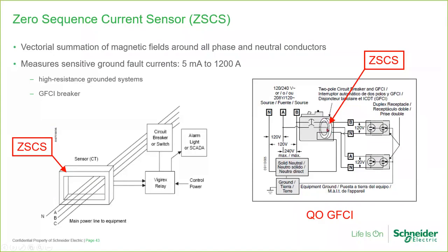That's why these breakers have pigtails, because unlike a normal breaker where you can just bring the load neutral to the solid neutral bus bar, we have to bring the load neutral to the breaker so that it's run through the zero sequence CT, and from the breaker is a pigtail to the solid neutral, or you can use the new plug-on neutral breakers to eliminate the pigtail.